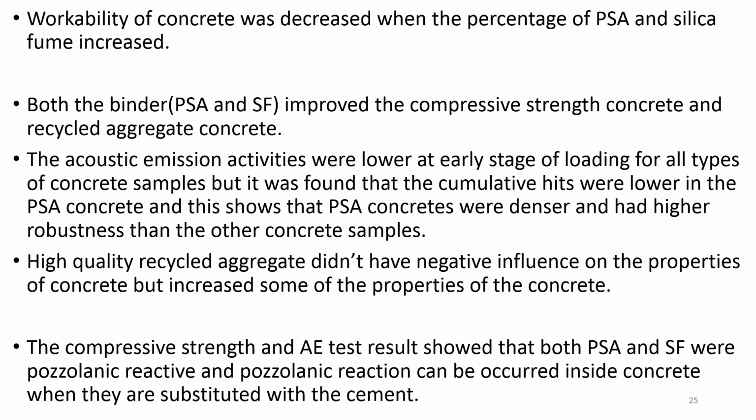High quality recycled aggregate didn't have any negative influence on properties of concrete, but increased some of the properties of the concrete. The compressive strength and AE test results showed that both PSA and SF were pozzolanic reactive, and pozzolanic reaction can occur inside concrete when they are substituted for cement.